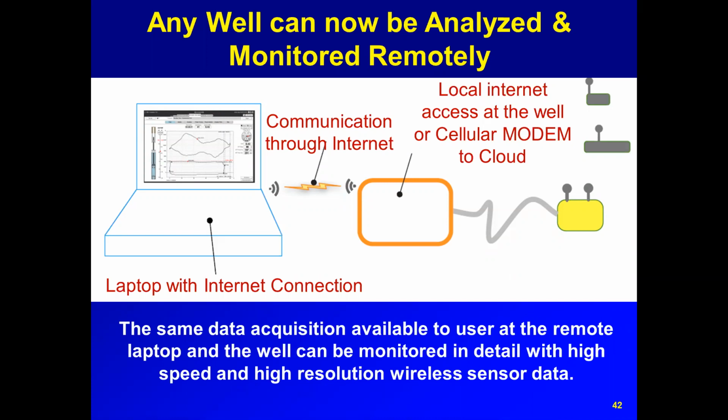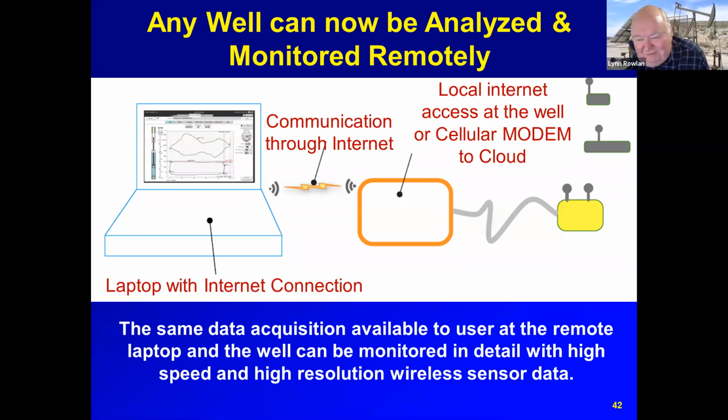Awesome. Okay, so now we have a few questions. What's the best pump to run with wells still making sand? Well, sucker rod pumps really don't like sand. There's a pump called a Muth pump that has a very tight clearance. Or you can use a very open pump clearance because the sand grains will fall through.